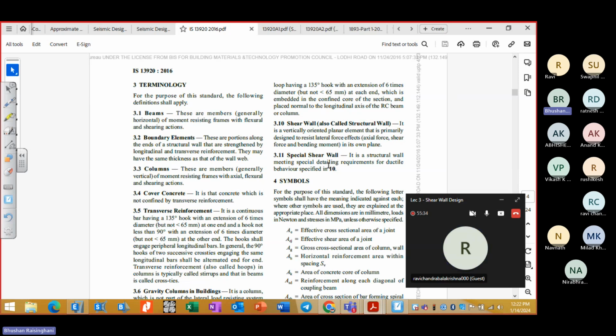gives accurate FEM results. ETABS is also developed by the same company, but it has a different output compared to SAP 2000, whereas SAP 2000 purely works on FEM. So F11, F22: in your x direction the shear force and moment, y direction shear force and moment, z direction, that is 6 degrees of freedom, and I think it also has warping forces.